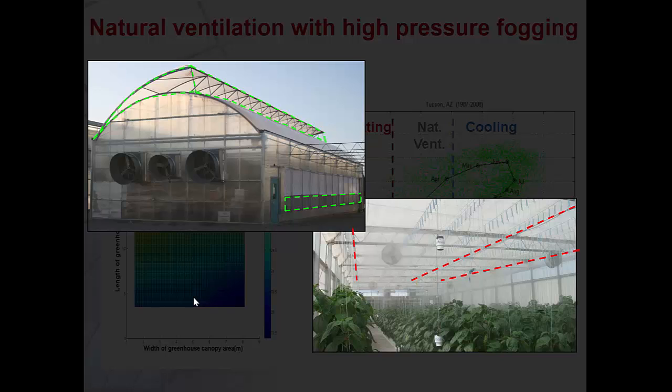If designed and installed properly, and with proper control strategy use, no water droplets will contact the crop or floor of the greenhouse below, which is sometimes a concern with the use of high pressure fogging systems within naturally ventilated greenhouses. High quality water filtration systems are also extremely important to reduce the problem of clogging nozzles with the use of high pressure fogging systems.